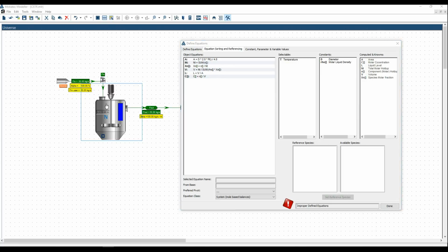Now you maybe are asking yourself how come the temperature is present as selectable variable when we did not use temperature in any of the equations of the CSTR system. We used the temperature variable in the reaction equations which we added to the CSTR system. There, in the reaction equations, we used sys dot prefix before the temperature variable, and by using that prefix we called that variable from the system where the reaction equations are added, and that is the CSTR capacity system. And that is why the temperature variable appears here as the selectable variable.